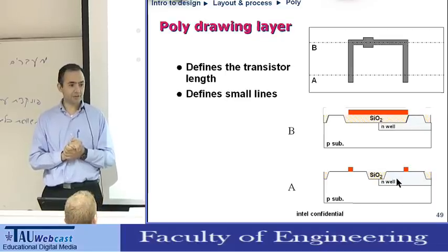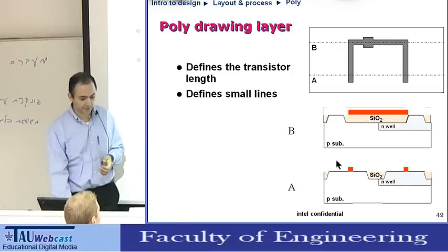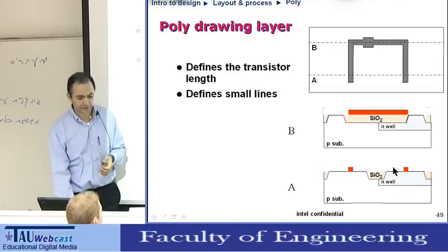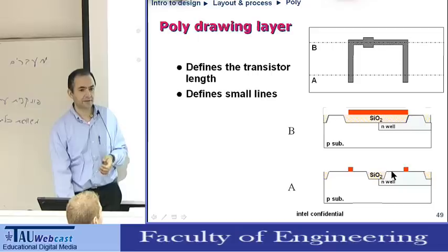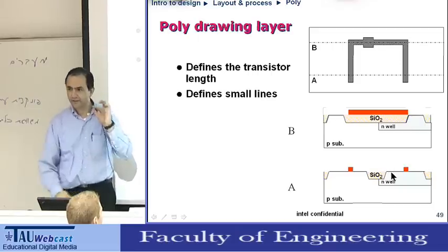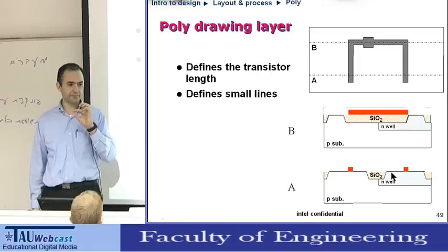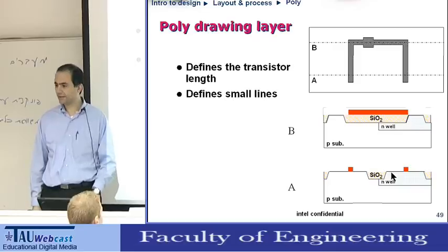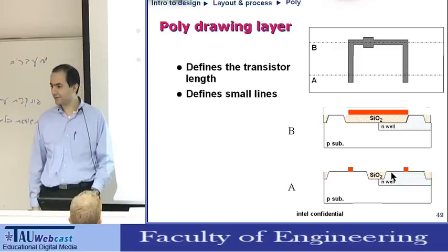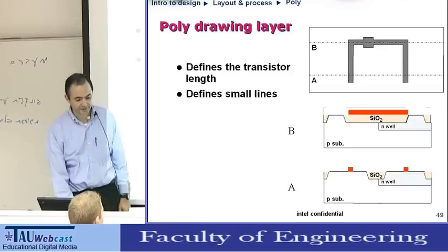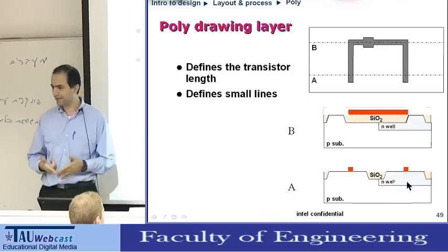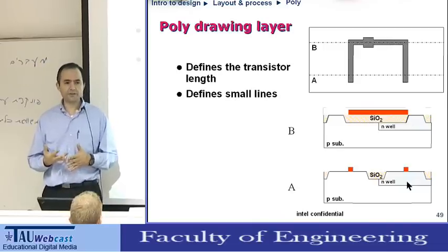Then we want to etch the oxide, because later we want to have contacts in here. We want to contact the silicon. So then we will etch the very thin gate oxide layer with an oxide etch. Okay? Again, we want this oxide etch to be selective in order not to etch the silicon below. And we can use an endpoint, a selective etch with an endpoint and an over etch. Okay. Why do we need the over etch?